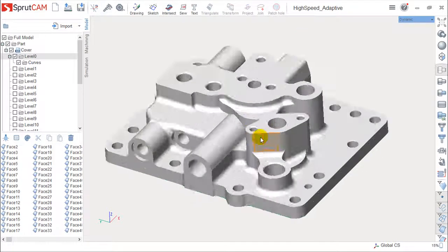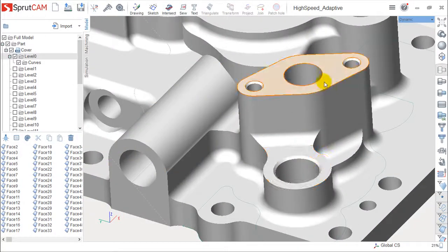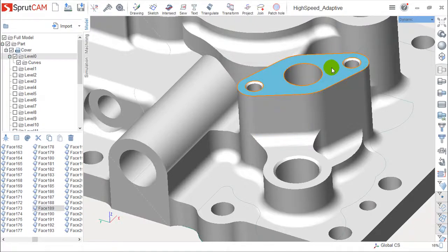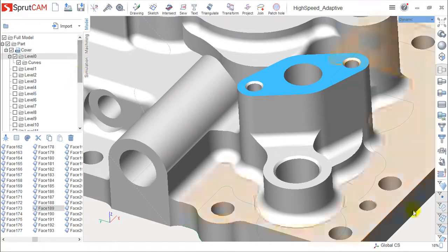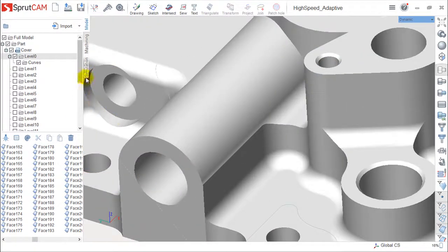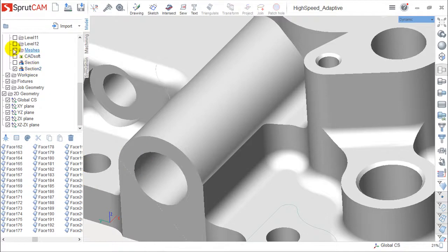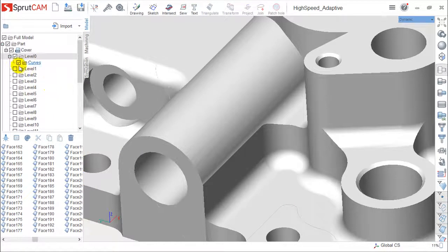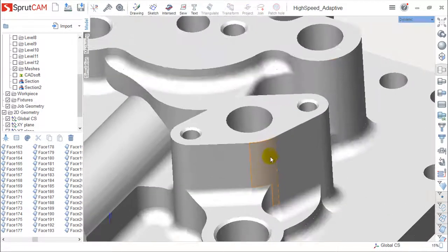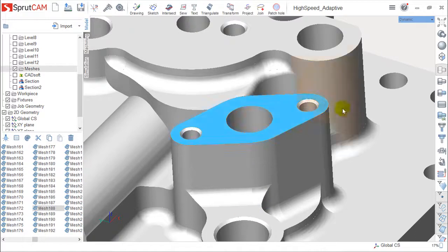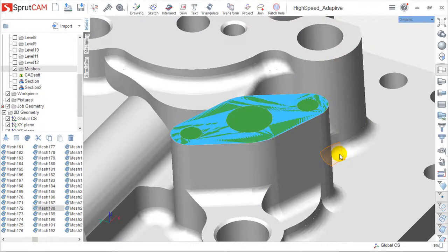Okay, for example, I will select this surface, I will do a patch hole, not in this particular case, sorry, but for example, let us open my mesh and okay, use my mesh, and now select this thing, patch hole, and we can close the holes very easily